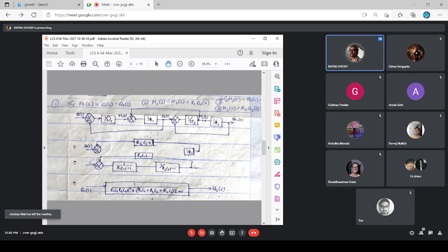Okay. So once you've got that, this is an independent one, I think you got this one, and once you understand that there's an independent feedback loop, I think this and this are clear now. Yes, ma'am. And then this is another feedback loop, a general feedback loop, not unity. Though it's going from above, it's actually a negative feedback at that. So then you simplify it: G by 1 plus GH of S. And G is obviously this one. This is the H.